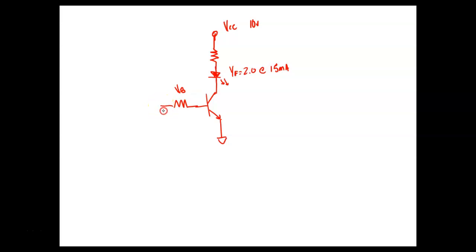And this right here is equal. Let's say VDD is going to be equal to 0 or 5 volts. So 5 volts should saturate it, 0 volts should turn it off. So, what will we do first? We're going to figure out what was saturated. So I'm going to say 5 volts should saturate it. So I say VRB would equal 4.3 volts.